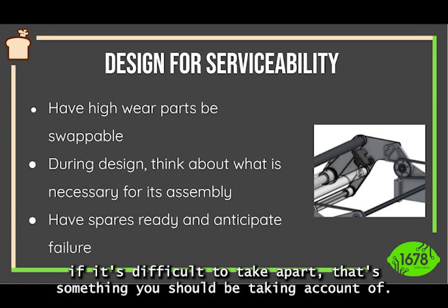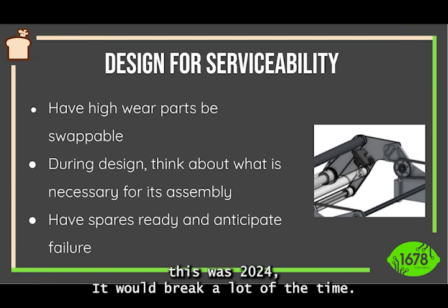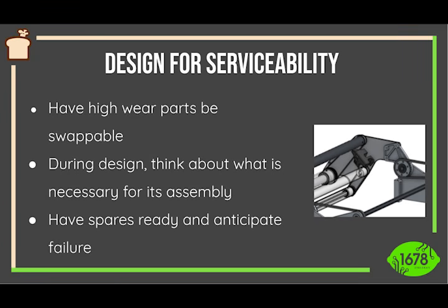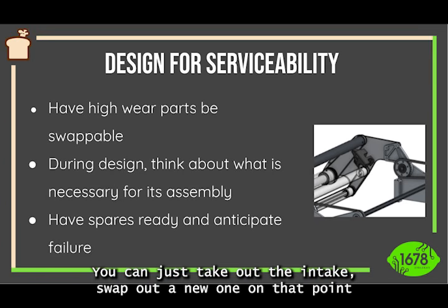If it's difficult to take apart, that's something you should be taking into account. For example, this intake, because it was 2024, it would break a lot of the time. And that's why we have three bolts right there. You could just take off the intake and swap on a new one.